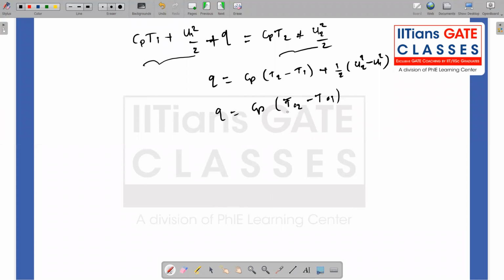So now the change in total enthalpy is nothing but either the addition of heat or removal of heat, that is governed by whether this T02 minus T01 is positive or negative. If it is positive, that means you are adding heat. If it is negative, that means you are removing the heat, right? So it's a straightforward energy equation. So by this point, you can recognize there is a change in total temperature. Unlike in our other cases, for adiabatic flow process, we treated T0 as constant. But in this case, it's not constant because there is a change in heat, right?